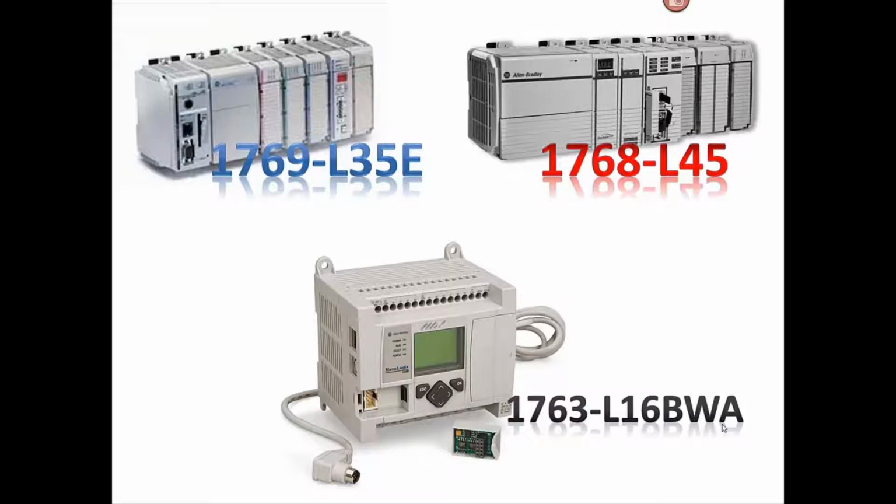Of course, that's assuming they're not broken, that they do power up and all of their features are fully functional. If you have an RS-232 port on each of any two processors, you can find some electrical interface to put between them, even if it's a computer with two RS-232 ports, and then write your own code in between them to do the communications.